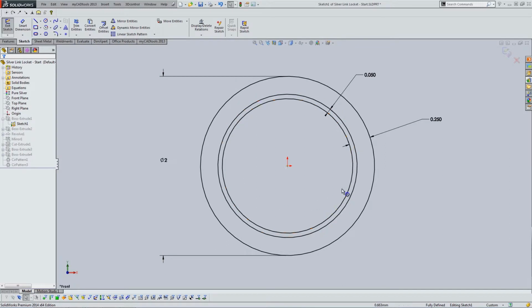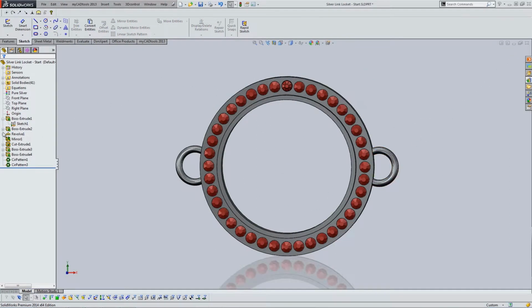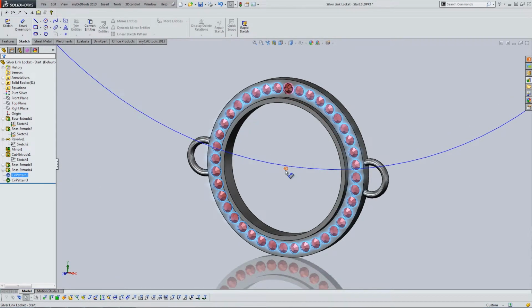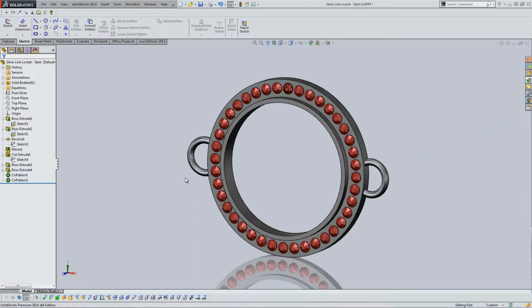Not only do we have one sketch that has dimensions that need to be scaled, but we have a lot of features that depend on those sketches. Completely different features, like there's a revolve here, and then there's a mirror function, and all sorts of stuff. There's even a pattern, right? If you remember patterns, if you double click, you'll see there's an instance number that dictates the number of patterns, and that's a dimension, if you will. So you've got to be careful with scaling. You don't want to scale this. You want to keep the same number of instances. You just want the sizes to be bigger. So here's where ScaleDimension really shines.